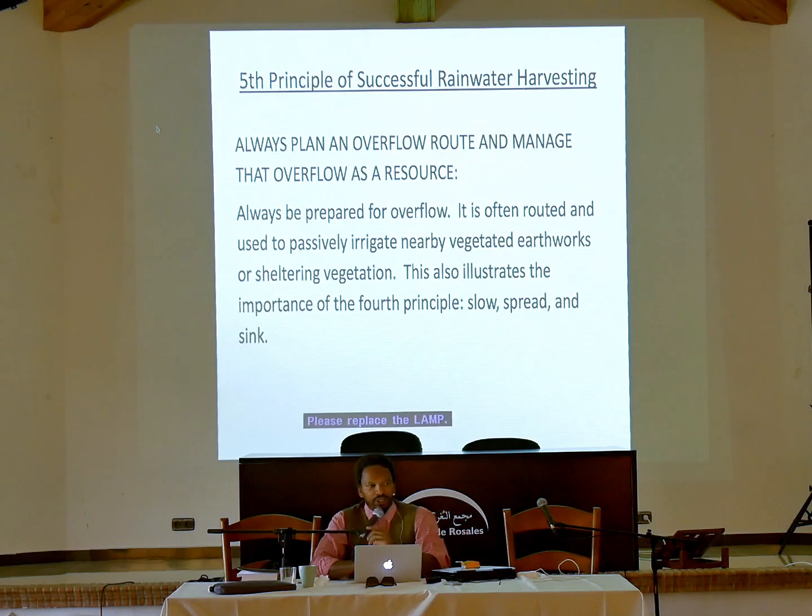One of the things that is often included in this discussion about earthworking and the management of water is the use of what we call a spillway. I think you guys have seen some of the spillways, or there should be spillways on the swale features or on the dam. There's a point when, say, the dam fills up and then the excess needs to go somewhere. For example, with the swale, the last place you want it to go is over the berm, because if you get a lot of water starting to run over the berm, then you get erosion. It starts wearing away all the soil, and then it washes away.